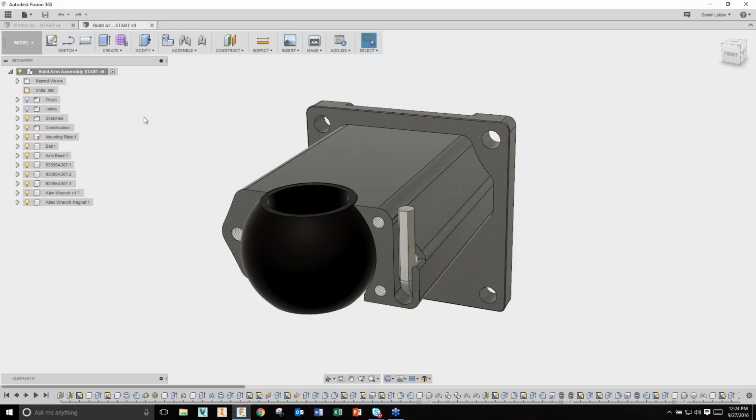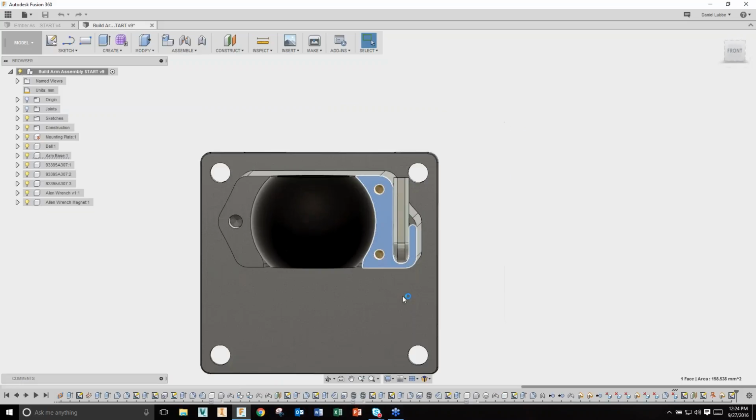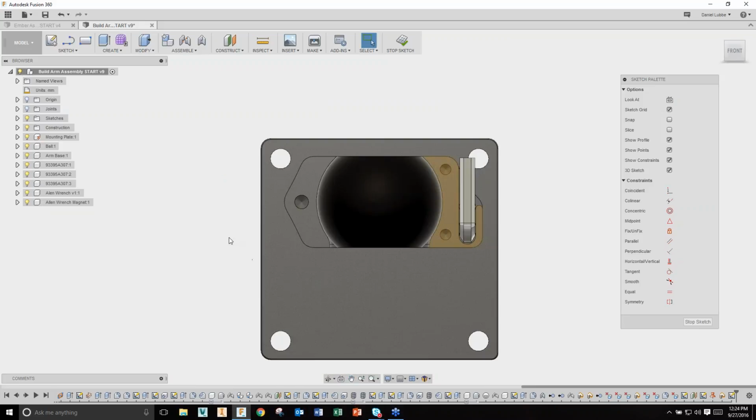Here in Fusion, we can do that, but we're actually more conducive to top-down design, where I'm in the context of my assembly, and I just have thoughts in my head of what I want to do. I'm just going to do it. And so hopefully you can start to see that as we go through. I'm going to start at my assembly by just creating a sketch on an existing component. Right? So I'm going to be automatically projecting those edges from where I started my sketch.